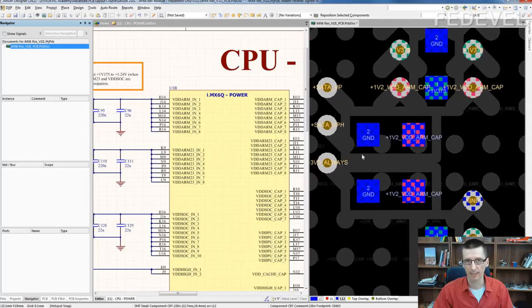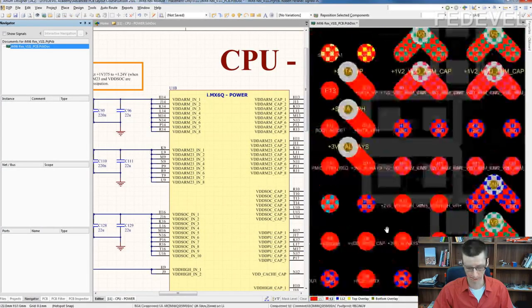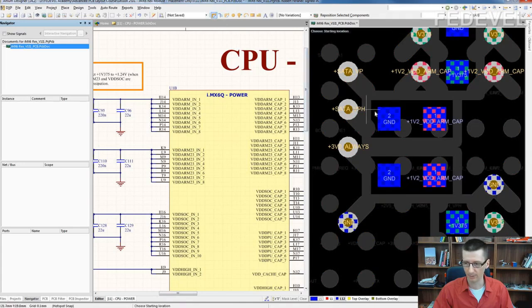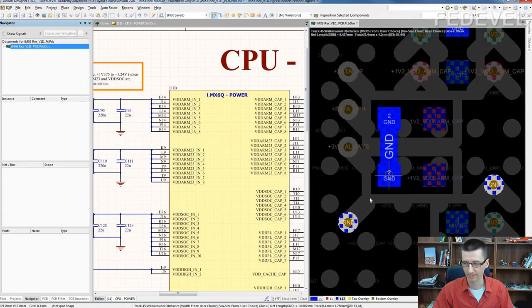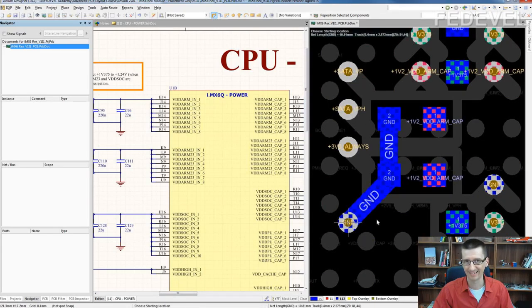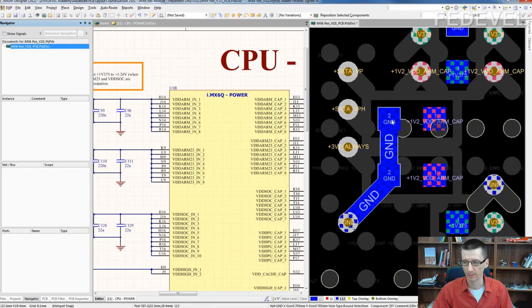Same for decoupling capacitors. We can connect them like this. Yeah? No, it's a better way to connect. What can we improve? We can connect each path to an individual via, and we can make this connection shorter. Always try to use as short a connection as possible.